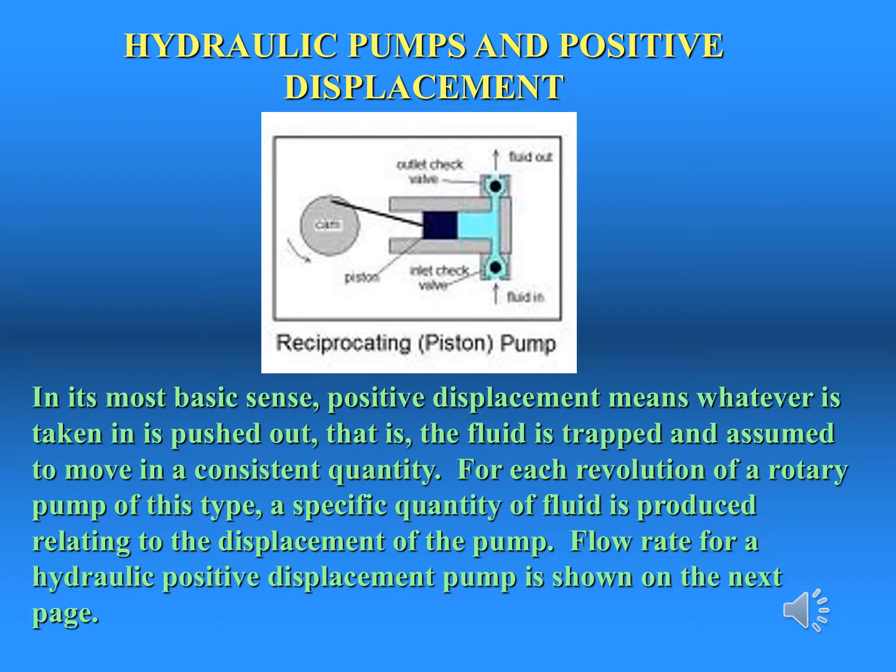In this illustration, a piston moves from right to left, causing an increase in volume. This results in a decrease of pressure. The decrease of pressure causes a net difference between the pressure outside and inside of the pump at the inlet port. The fluid, as influenced by a greater value outside, is forced to the inside, filling the volume.